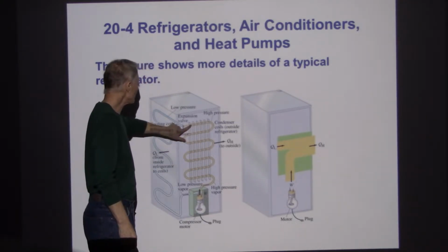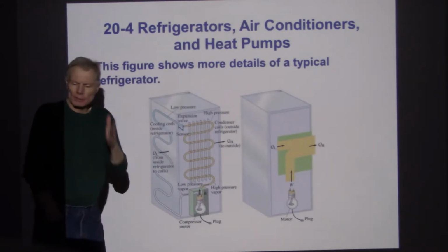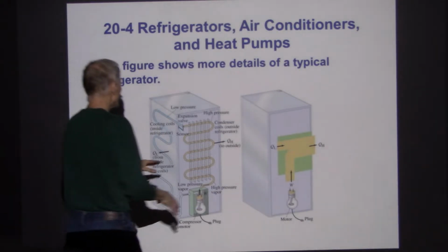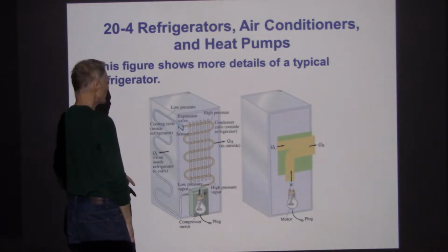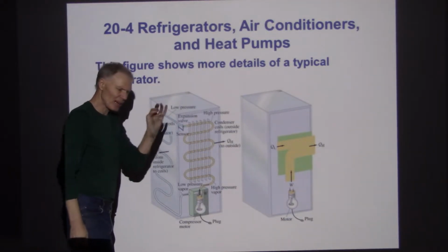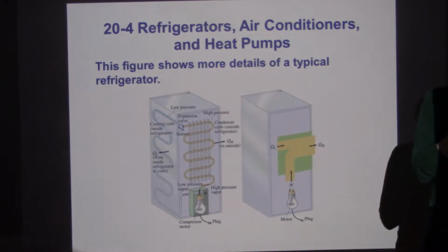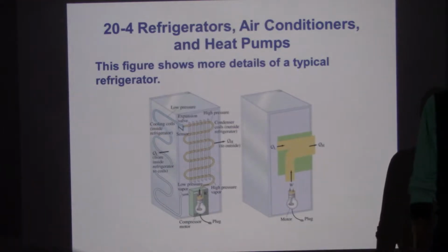And then halfway through the piping, we have an expansion valve. And that divides the plumbing into two different sections. There's this first section that the compressor is maintaining at high temperature, high pressure. But then there's this tiny opening, and we looked at some of this too. We saw that if something just expands rapidly, its temperature just drops.